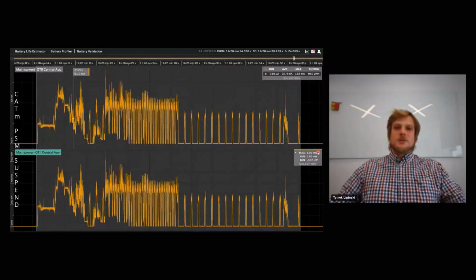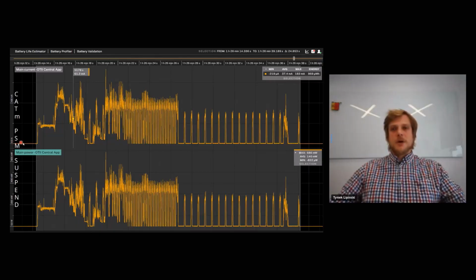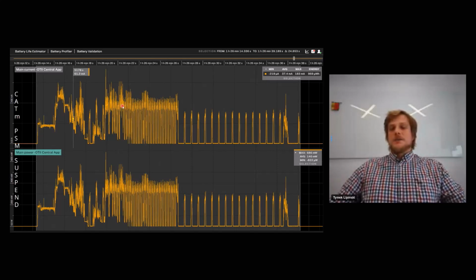Let's look at current consumption curves. So this is the first example. It's CAT-M, PSM suspend mode. Here, the modem was completely sleeping at below 4 microamps of current consumption. Then the modem either wakes up on its own, or we trigger it by pressing the on button. The modem loads the system, activates and configures it, starts searching for a network, finds the network, sends 1 kilobyte, receives 1 kilobyte, and then we have this unfortunate 5 seconds of doing nothing because we have the RRC keep alive.